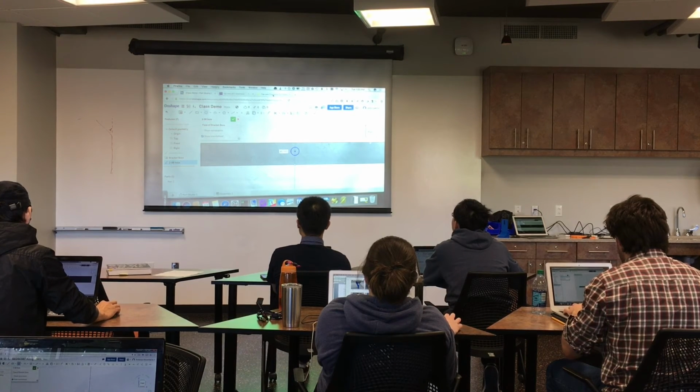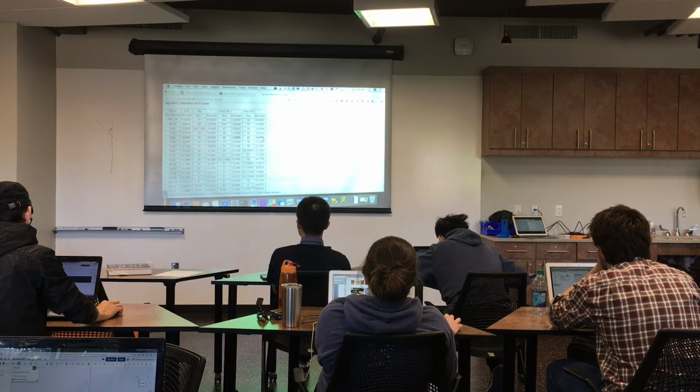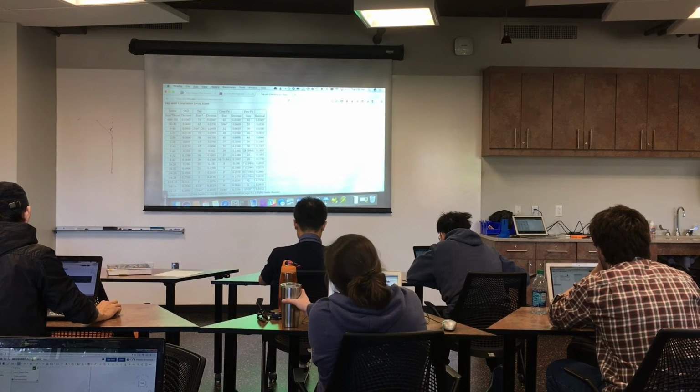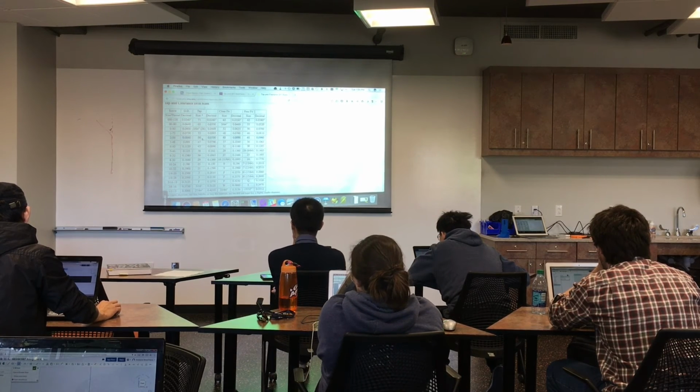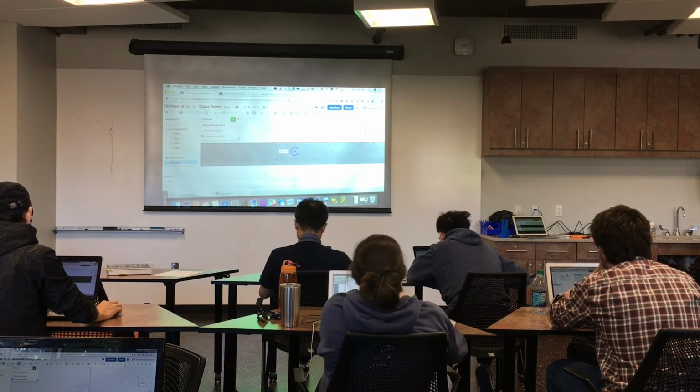And then we go back for a 256. We want to make this a tapped hole. So tap drill is a number 50, which is 70 thou. So I will get my dimensioning tool. You can hit D or you can grab it.